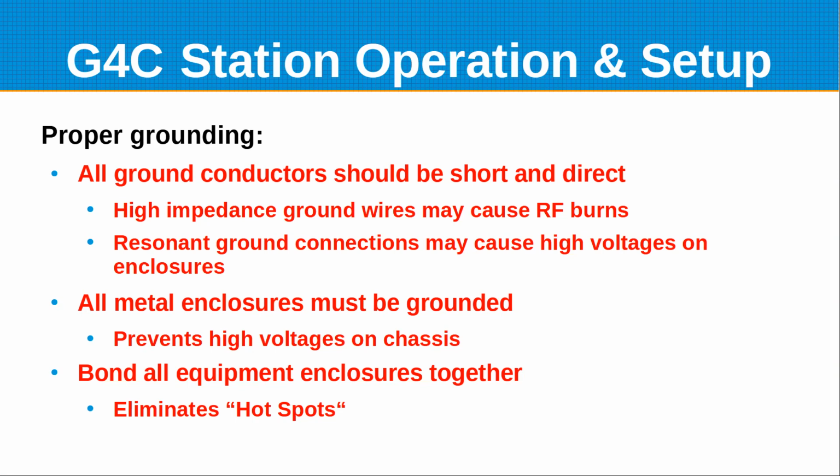You should ground all metal enclosures, preferably with your single point ground, but definitely some way to tie them together so they're all at the same potential, so that you don't have a voltage difference between one equipment cabinet and another one, which can give you a healthy shock or burn.